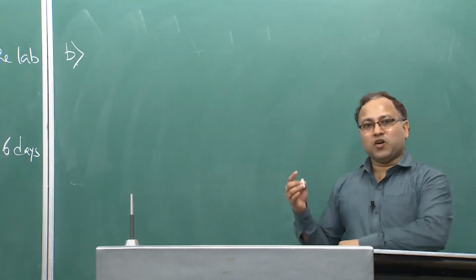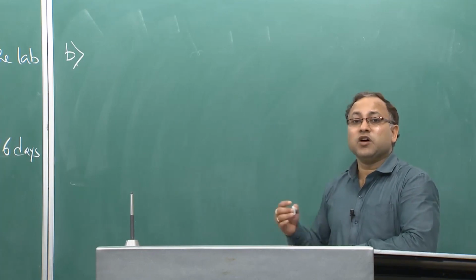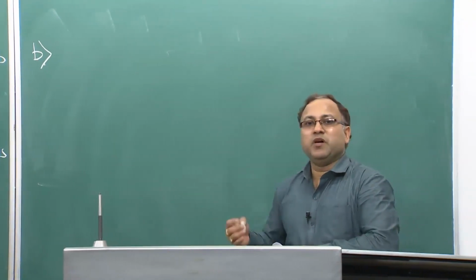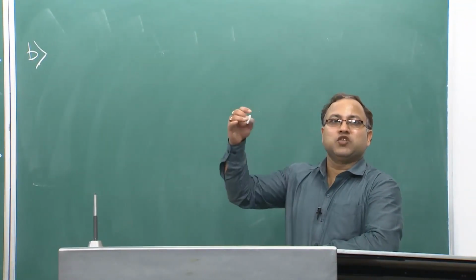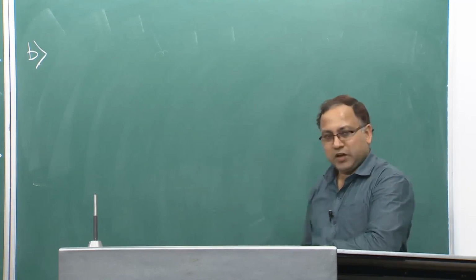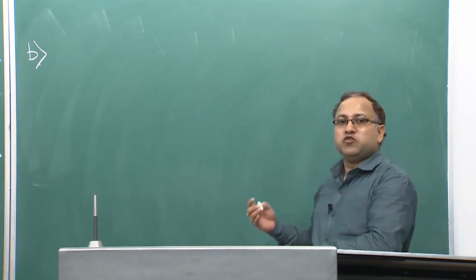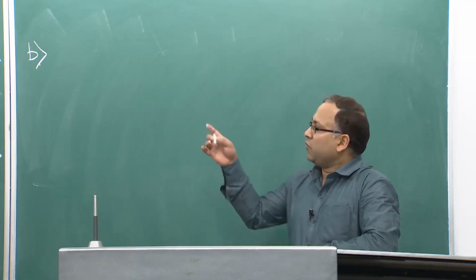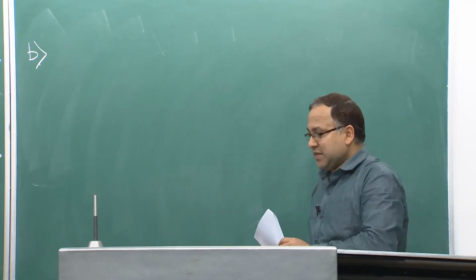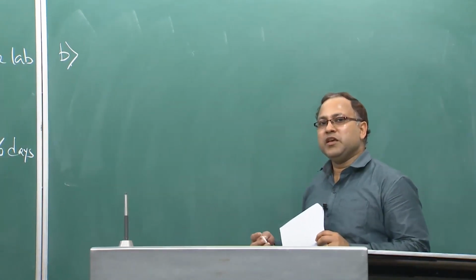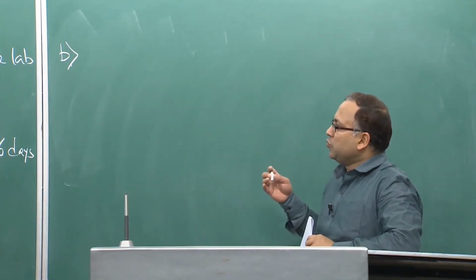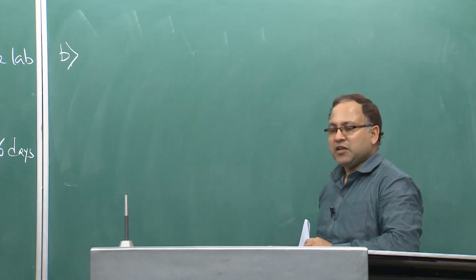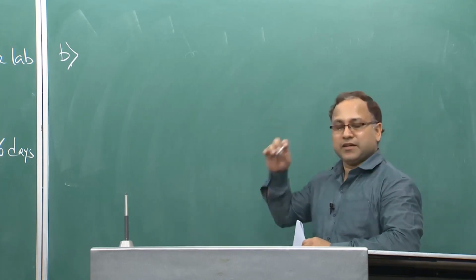draining out either from the top surface or from the bottom surface because of some kind of impermeable layer situated at the top or as well as the bottom. Okay. So, if that situation arises, then what should be the time required for 50% consolidation. So, let us see how much time will be more to get 50% consolidation for single drainage system.